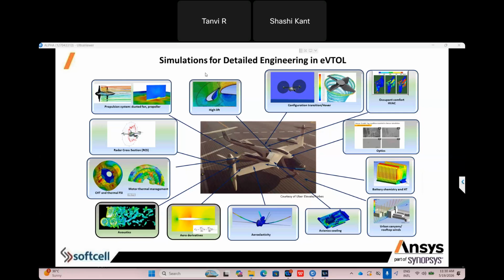One is called manual, whatever people in the industry currently use at a basic level. The second is parametric optimization. Third is topology. Parametric means you can define multiple locations of the vent, and using Python code, or if you want to do maybe 5 to 10, you can do it manually also. Let's suppose you want to create 100 iterations of the location for the vent, you can do that using Python code. Once you've created all these iterations, you just put it on solve.